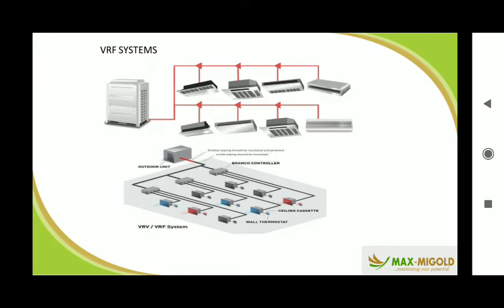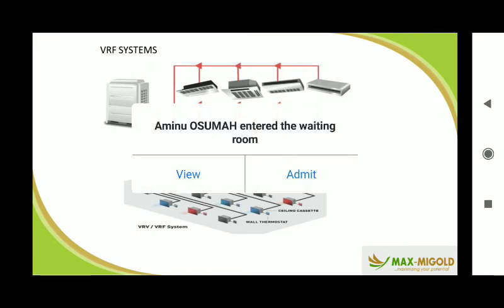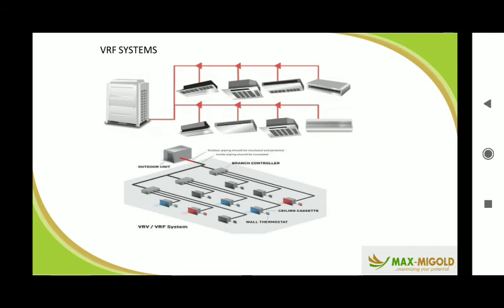The benefit of this system is that it saves energy. It has multiple compressors that work together. They sense the heat load coming in, and as they sense the heat load, what do they do? They reduce the number of compressors working. If we have 1 or 2 persons within a space, this system has the capacity of shutting down multiple compressors and allowing only one compressor to function, meaning you are working less. You get my point? So most buildings today are going for refrigerant flow.